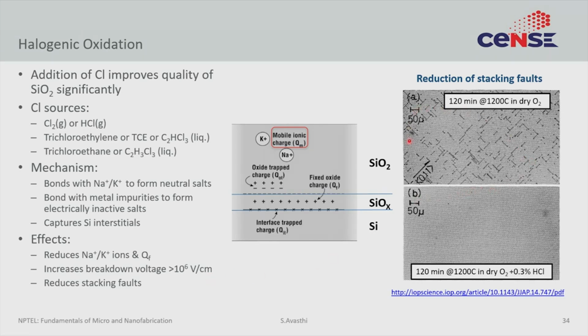So, we have taken a silicon wafer in this figure, grown the oxide, and then stripped the oxide away. So, we can actually look at the interface at the silicon surface again. And if you look at the silicon surface, you will actually see these straight lines which are actually stacking faults that are forming on the surface as you are growing the oxide. So, this is especially acute when you are doing the oxidation at high temperatures. More on that in a minute.